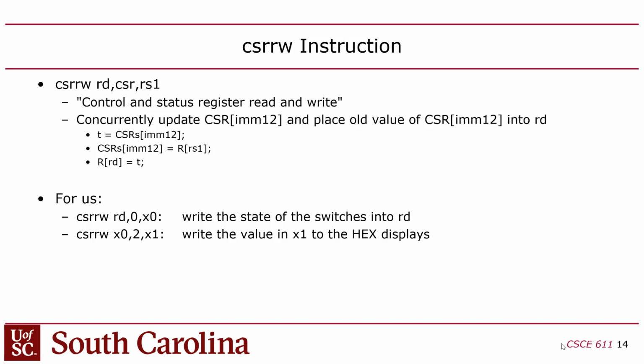So the actual name of this is Control and Status Register Read and Write. It's a little bit confusing though, because it's called Read and Write, and it really means that. It always reads and writes. It does both. So you can't just write a control register. It forces you to read a status register, and you can't just read a status register, you have to write.